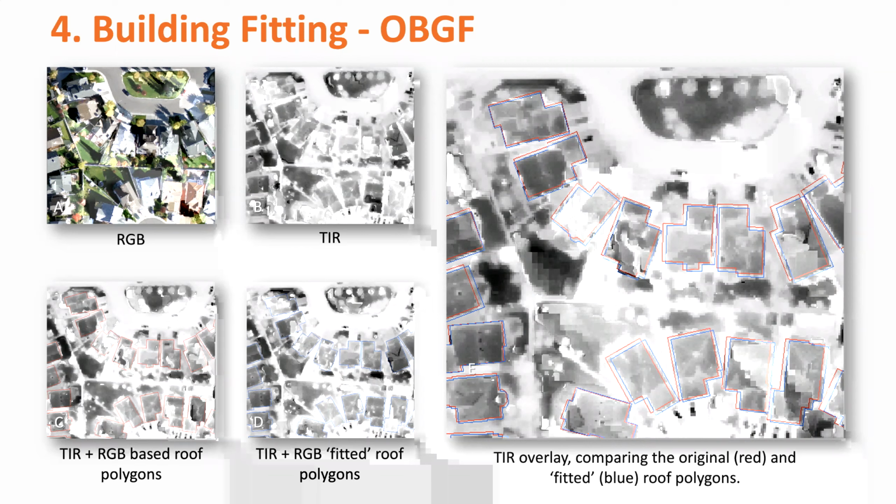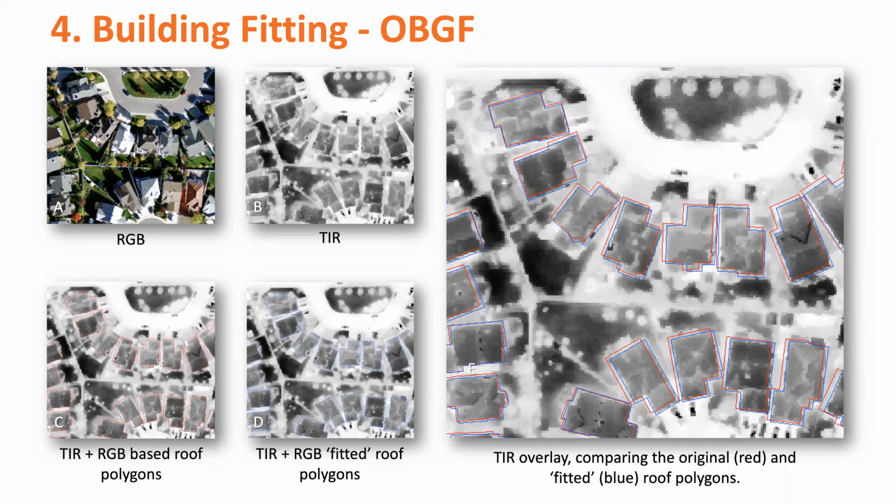normalize the data set so it appears as if all the images were collected at the same time. The imagery have been corrected for atmosphere and for wind and for other things. So what we truly get is temperature of buildings. The energy that is emitted from a building. It's not reflected energy. Thermal radiation is not reflected, it's emitted from structures.